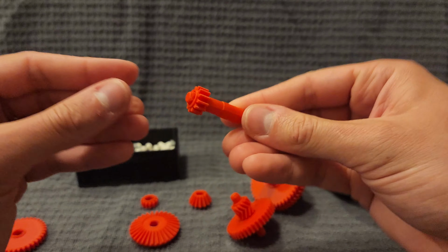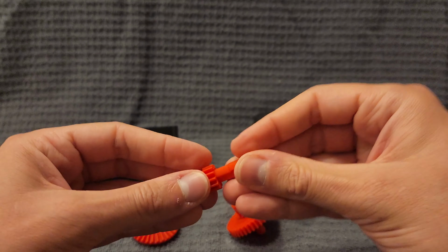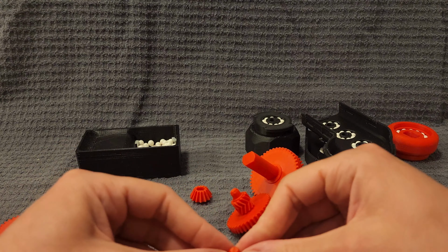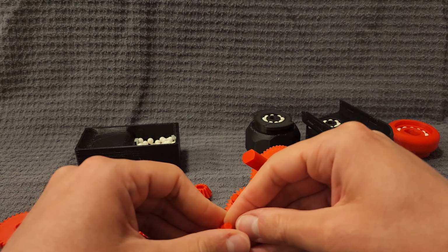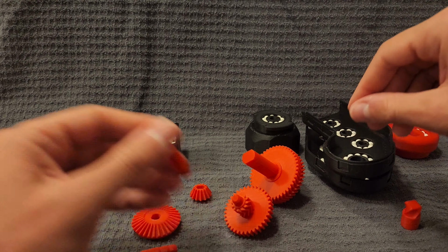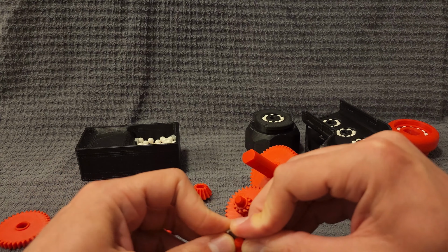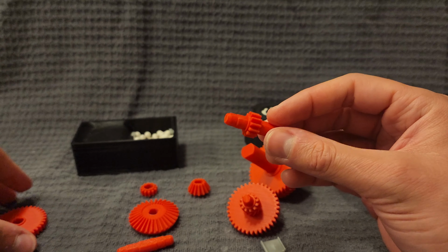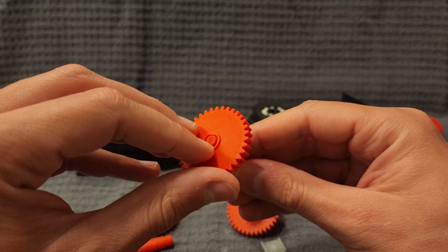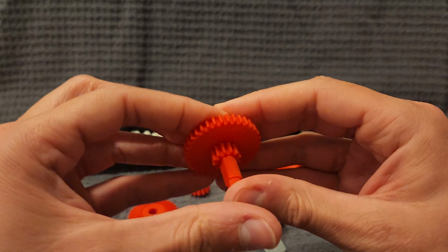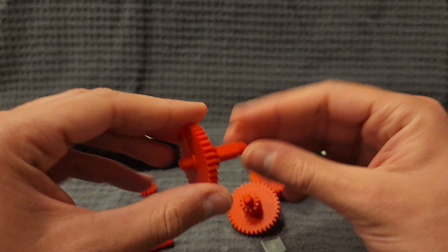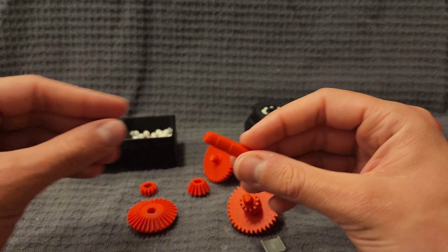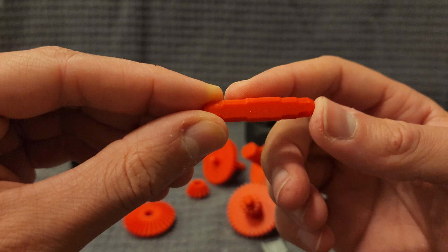The third shaft is a similar process, but you start with a smaller gear. Again, the face width of that gear has to match the one on the spur gear, the larger one that you assembled on the second shaft. Sometimes the gears are a little bit tough to insert, so you may need some help from other components. Make sure you don't grab the teeth with a pair of pliers because you might damage the teeth. And then you gotta put in the bigger spur gear that has the thinner face width to complete the third shaft. Let's move on to the fourth shaft.